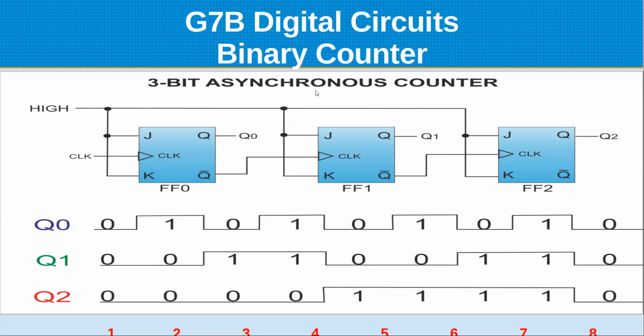So a 3-bit counter can count up to binary 7. Things that didn't start at 0 and go to 7, say, 0 again. Well, this is the 8th clock pulse, so it's going to roll over to 0.